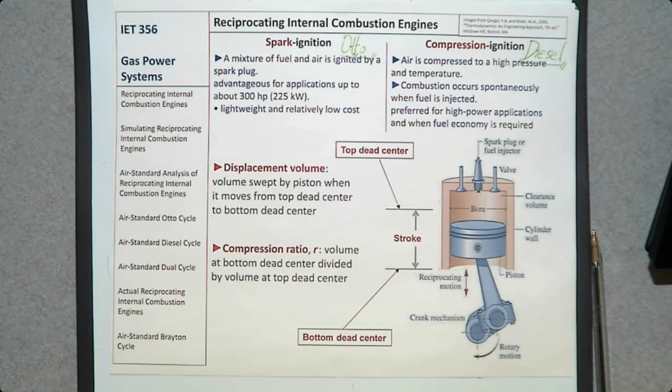The problem is that if you compress more, the temperature and the pressure inside the piston cylinder are going to dramatically increase. So when there's fuel inside, it's going to self-ignite. We don't want that to happen. We want to increase the compression. What can you do? We can just add air in the system without fuel. Can we do that? Yeah, we can do that.